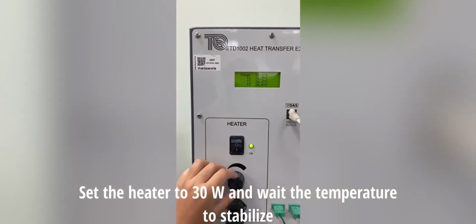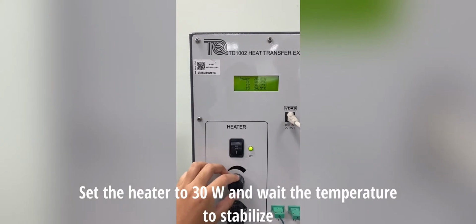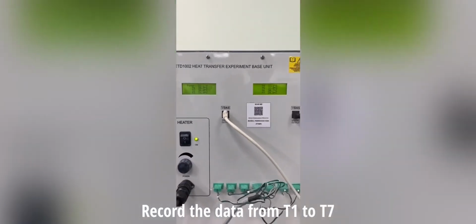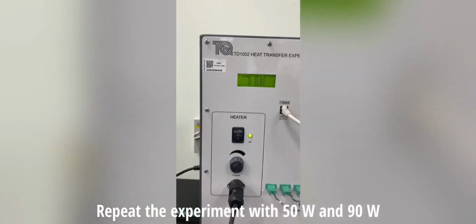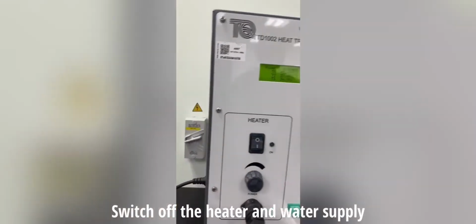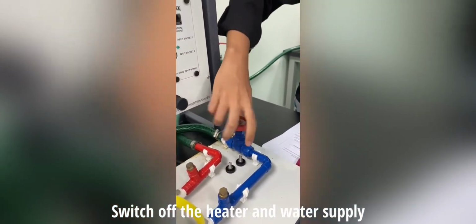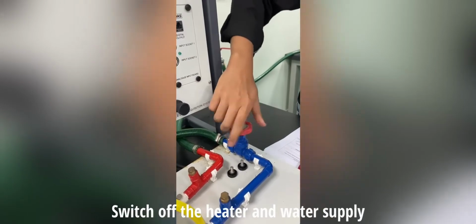For the first data, we set the heater to 30 watt and wait for the temperature to stabilize and record the data from T1 to T7. Then we repeat the test with 50 watt and 90 watt. Repeat the test at one or more heater powers greater than 30 watt. And then we switch off the heater and water supply after we finish the experiment.